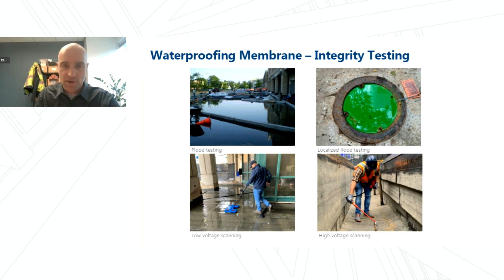It's important before you start one of these tests to make sure the structure can support the weight of water. In the cases where the substrate is sloped, it may be necessary to install dams to minimize the amount of water that's on the surface of the slab. If the slope is particularly steep, conducting a flood test might not be practical. Electronic leak detection is an alternate to flood testing.